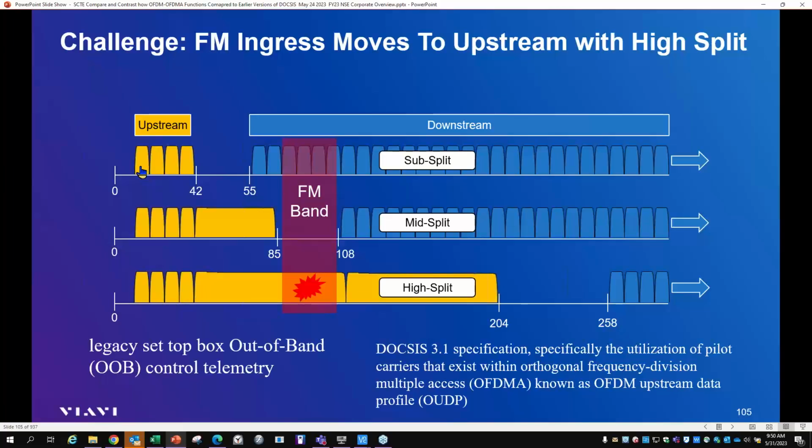You guys have probably heard of the term unity gain upstream, right? But think about noise unity gain, noise coming from subscribers and all those types of things. Well, the same concept that Woody just brought up, when you have multiple FM ingress, for example, right? And then the compounding of that is going to hit back on the upstream again, depending on the bandwidth of your network. But yes, right now, FM for most systems is a downstream related issue. But as we move forward, it will become an upstream related issue. So yeah, compounding noise.